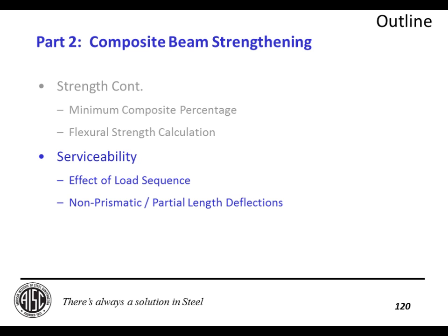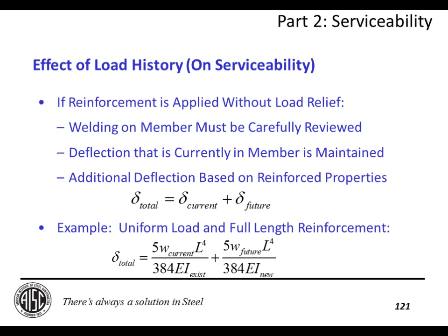Serviceability, the effect of load sequence. Really this comes down to whether you want to jack the existing load out of your member or not. Again, if you're not going to shore out or jack out the existing load, you should carefully review welding on the member because, again, it renders pieces of the member ineffective temporarily. And any deflection that is currently in the member is going to be maintained.